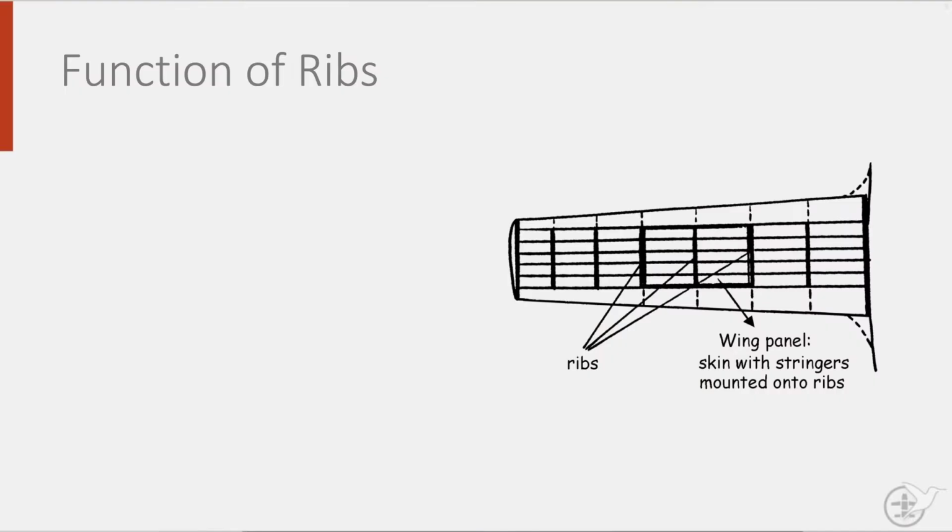Today we will look at an important structural element in wings, the rib. Ribs have an important function in wing design. They ensure that the wing maintains the aerodynamic shape or profile so that lift is generated as designed by the aerodynamicist. As an aerodynamic profile is defined in flight direction, ribs are often placed in flight direction also, even though sometimes it is easier from a manufacturing point of view to place them perpendicular to the spars.